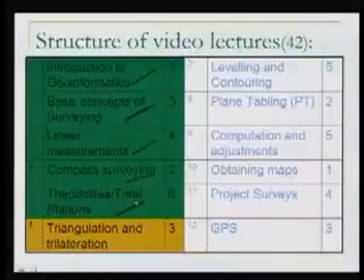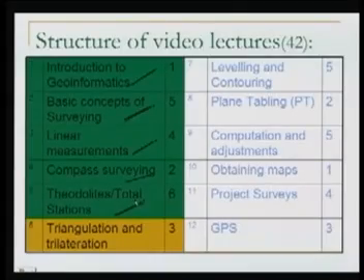What we will do today, we will begin with lecture number 1, because surveying is basically about the measurements. Two basic measurements there are, angle and distance. For distances we have seen the methods which are like chain, tape, invar tape, or maybe the EDMI. Now for the angle measurement we can make use of a device like compass, but that is not very accurate. We have seen the reasons why it is so. So the more important device or more useful device here in this case is the theodolite.